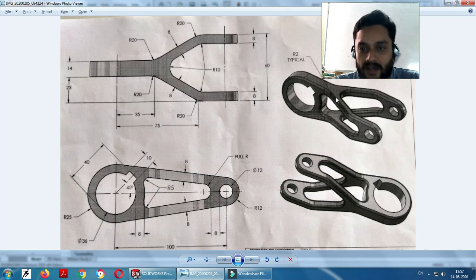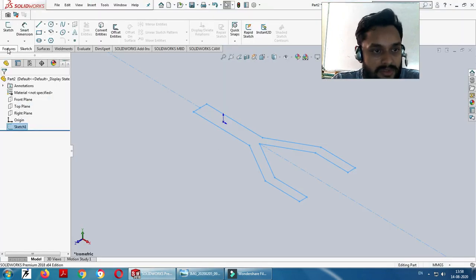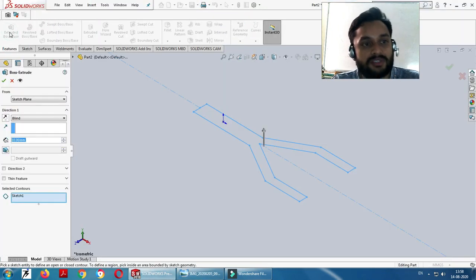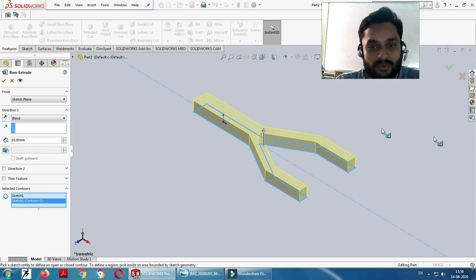Now let's extrude this sketch, and for that you require the extruded depth. So the extruded depth, you can read it from the drawing, it is from here to here, it is 25. So it will be 50 mm extruded depth, correct. So I'm using the extrude command. I'm simply selecting the sketch. So depth will be provided normal to the sketching plane, that is your extrude command, correct.